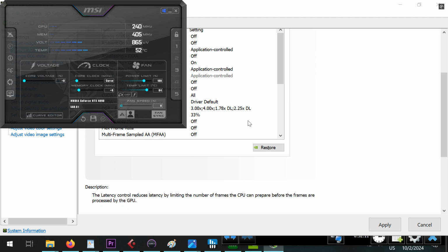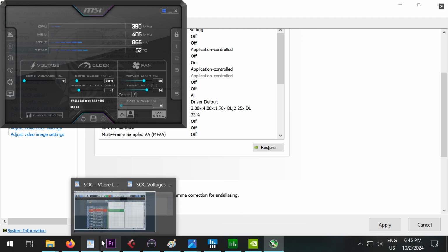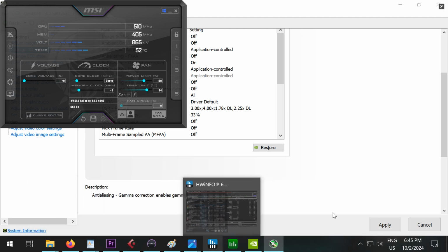I have 3 cables connected, so each cable is 150 watts each. That PCIe cable, actually. 150 plus 150 plus 150, which is 450 max. For the newer GPUs that have an OC profile of like 600, which is insane, I feel like this is exactly how cables are melting.